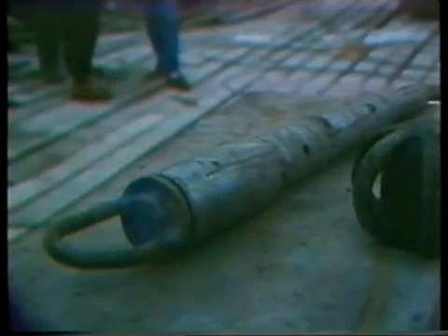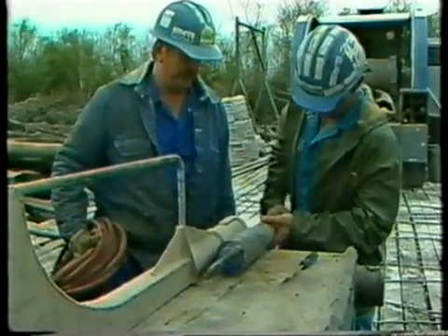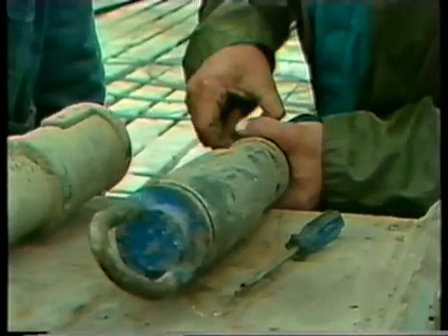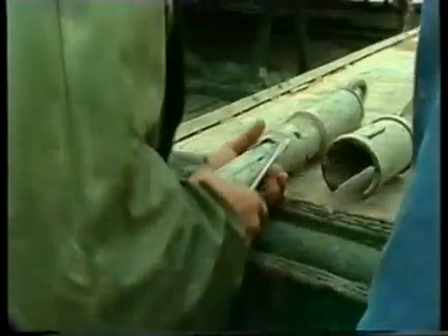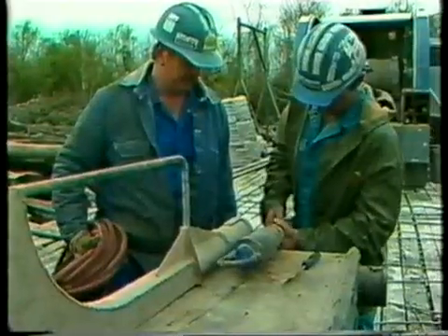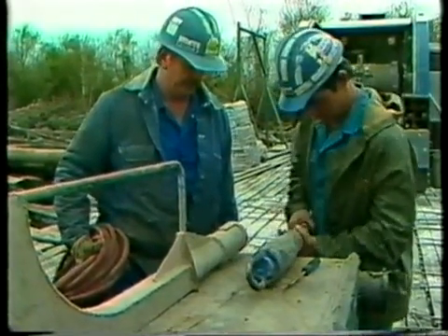The cable attachment mechanism, shown here, or head as it is called, is also designed to be the downhole weak link or break point of the cable system. Should the tool string become stuck in the hole, this weak link is designed to break before the cable snaps, avoiding costly fishing jobs for wireline.